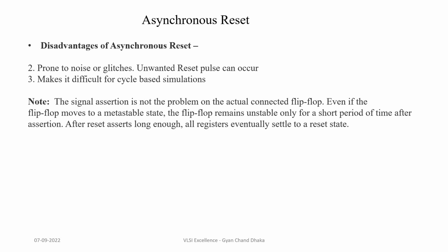The second disadvantage of asynchronous reset is that it is prone to noise or glitches. Unlike with synchronous reset, where glitches or noise can be eliminated because the reset pulse is detected only at the active clock edge, here the reset is asynchronous and can be applied at any time to the design. So any kind of noise or glitch pulse can also reset the design, which is not expected. Also, asynchronous reset designs make cycle-based simulation difficult.